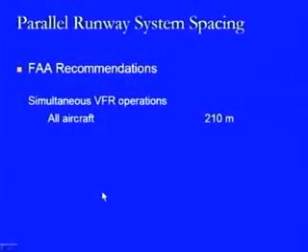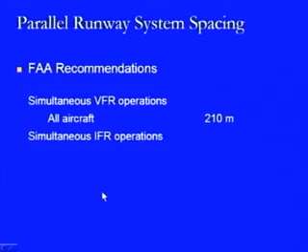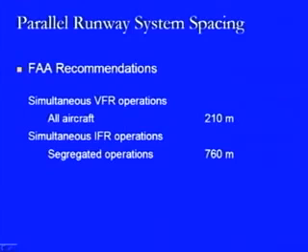Then further, there are some more recommendations of the Federal Aviation Administration, and it says that under simultaneous VFR conditions for all aircraft, the spacing can be 210 meters, whereas for simultaneous IFR operations under segregated conditions it can be 760 meters.